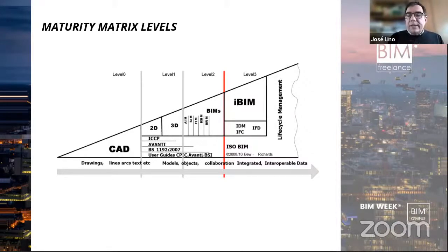And level 1 is when you start to do BIM, okay? But you are using simple models, usually only to model the geometry. You are sharing using files, okay? You send your file to me, I will send my file to you. Not much sharing here, but we are already using probably a mixed model between traditional drawings and BIM models with scarce information.